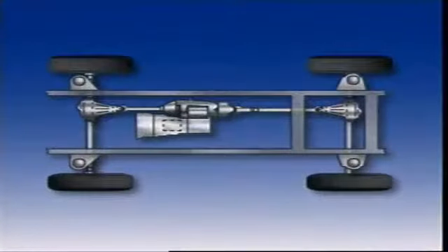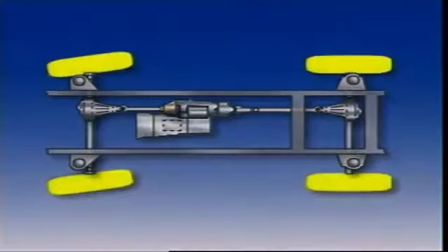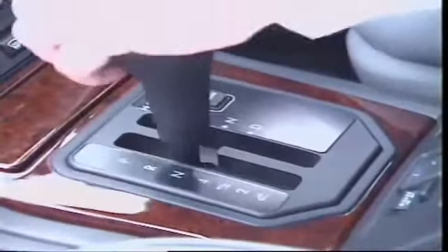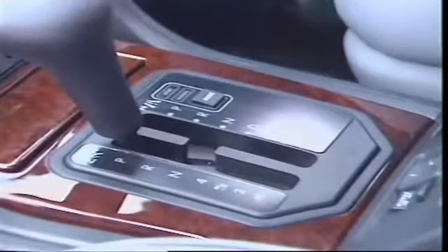Constant four-wheel drive uses a third differential in the transfer case. It allows for the difference in speed between the front and rear wheels during cornering. The driver can still lock the front and rear axles together by moving a separate lever as in a conventional four-wheel drive, or by moving the main gear selector. This is called a differential lock.